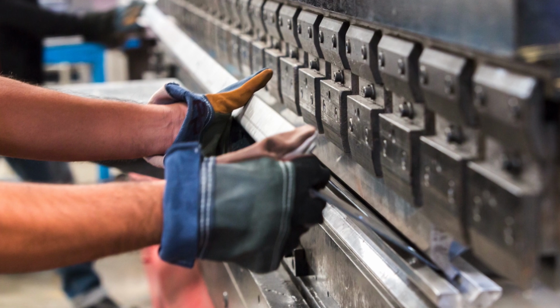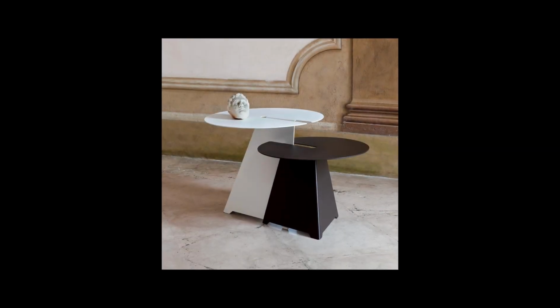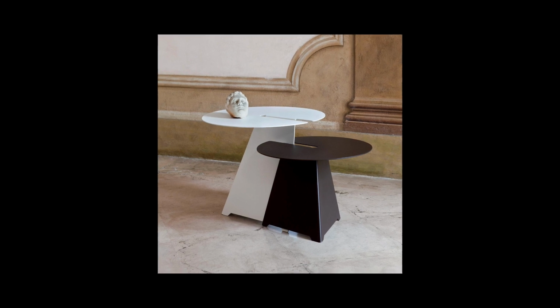You can think of this manufacturing method as a type of origami but with metal instead of paper. So what you do is that you cut out the necessary shape from a large piece of metal sheet and then you bend that into the desired shape of your product. And the beautiful thing about this is that it requires almost no tooling and also very little machine setup. And if one is creative with sheet metal design, it's actually possible to create some very exclusive looking products at an extremely low per unit cost.